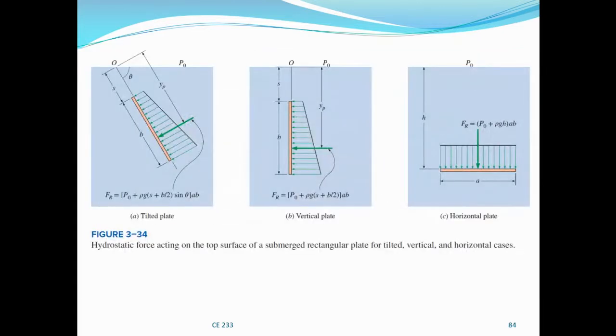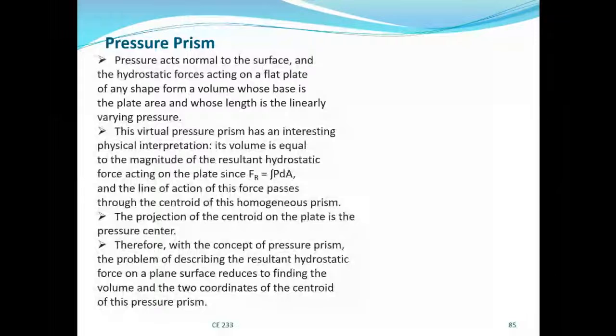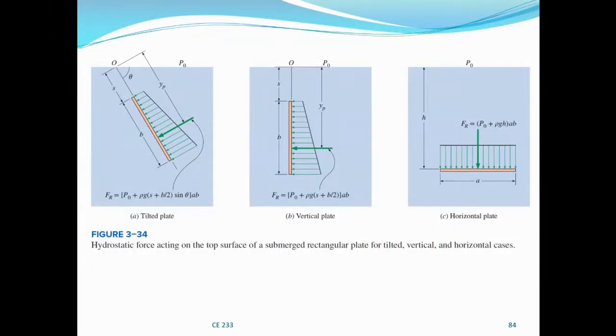Now, before we go to an example, I will summarize again, in a more pictorial form, what I presented. For a horizontal plate, you have a uniform pressure distribution, and the resultant hydrostatic force passes through the same point.